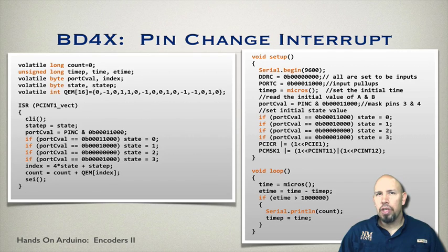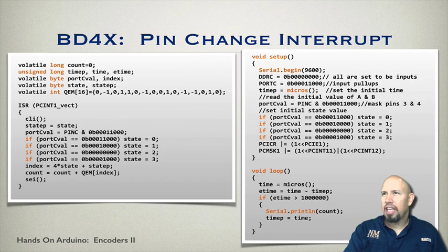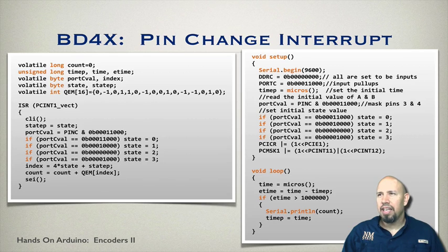As a result, when the compiler goes through to compile, it sees that the main program never accesses the interrupt service routine, and so it tends to shut down any global variables if they're only used in that place. That's why we need to use volatile, so that the compiler won't automatically just ignore them.